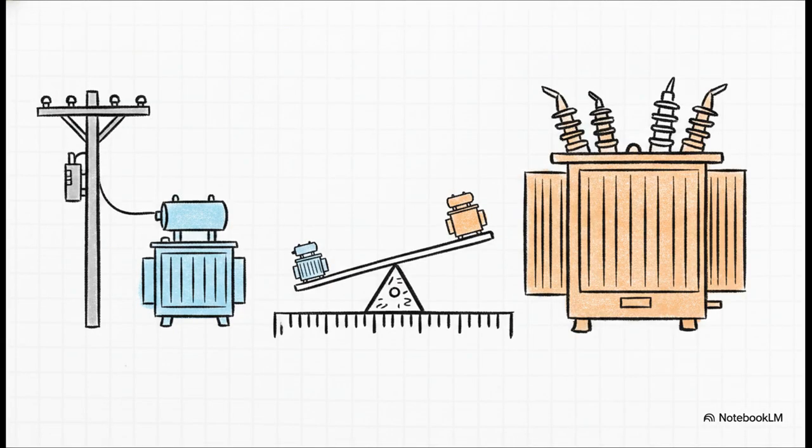And this brilliantly illustrates why power engineers absolutely rely on the per-unit system. It completely strips away the physical size of the transformer from your math. Power transformer impedances typically fall into a very narrow range of 4 to 8% in the per-unit system. This is a total game changer because it allows you to directly compare a 500 kVA distribution unit to a massive 50 MVA substation unit on the exact same scale and use both directly in fault current calculations without ever doing those tedious voltage level conversions back and forth.